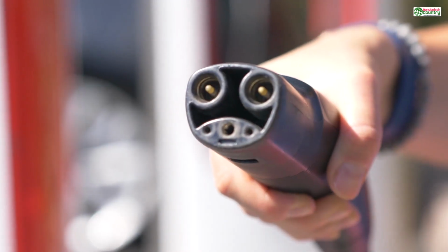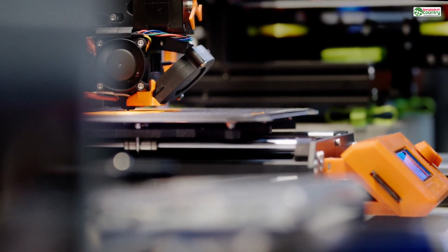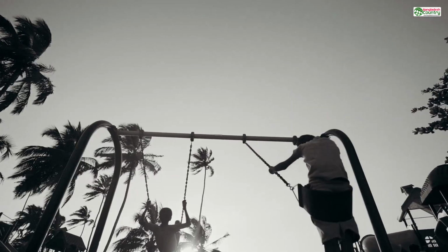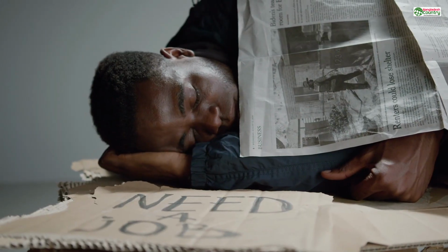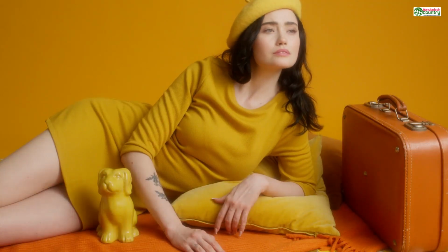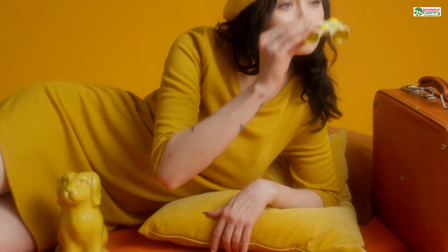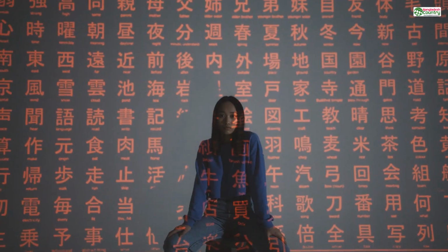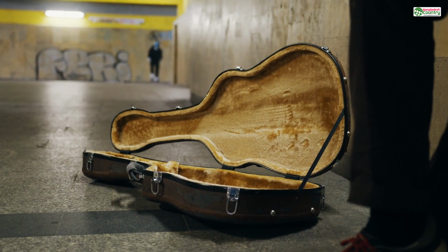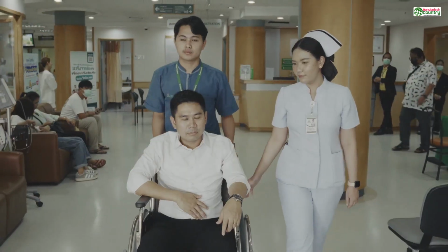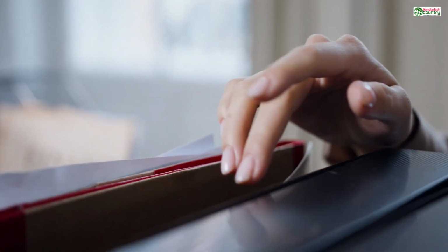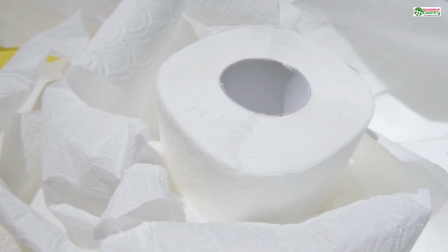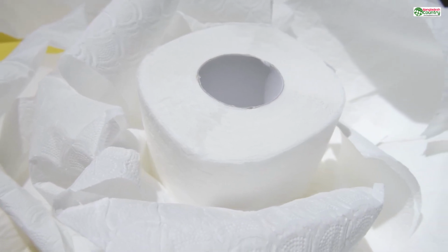Now let's swing to the other end of the spectrum. What if you need your part fast and cheap? Maybe it's just a rough prototype to check if 2 pieces fit together. Maybe it's a functional bracket that's going to be hidden inside a machine, and no one will ever see it. In that case, you don't care about a perfect finish. You care about strength and speed. This is where you choose a high layer height, say 0.3 millimeters. Using our paper analogy, this is like using that thick construction paper. Now, to build that same 1-inch tall object, the printer only needs to draw about 85 layers instead of 254.